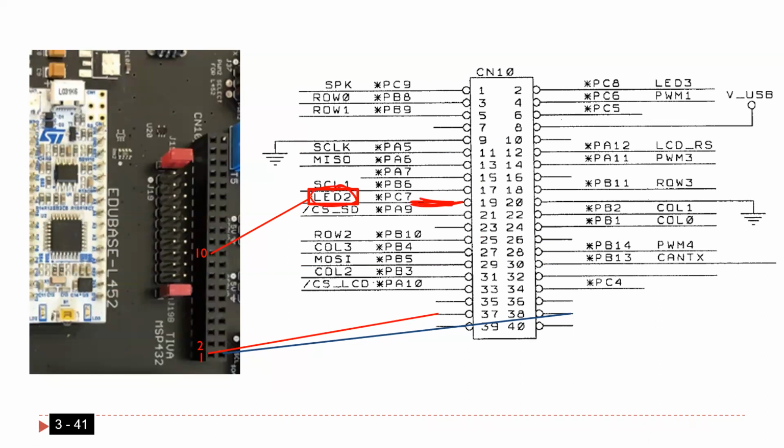Okay, and I mapped from here to here. It took some time for me to figure it out, because when I look at the diagram here, you find that this pin is number 11 from here, not number 10. However, I found that I think they don't connect this one. So I found that this one actually is number 10. When I put it here, it worked.